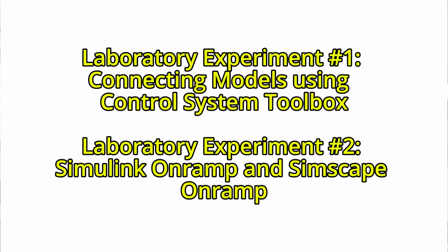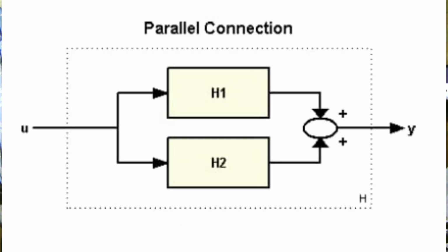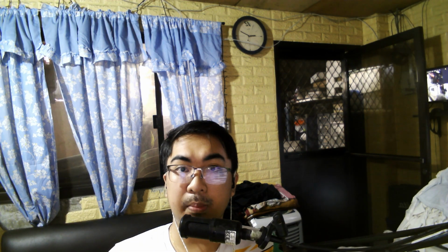In the first 2 lab experiments, which involve modeling and simulation foundations, I learned how to connect models using MATLAB's Control System Toolbox. I practiced series, parallel, and feedback connections, and even built MIMO, or multiple-input, multiple-output systems, by concatenating inputs and outputs. This gave me the foundation to represent complex block diagrams mathematically.